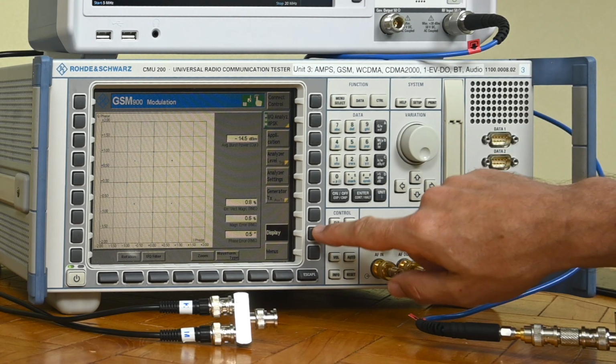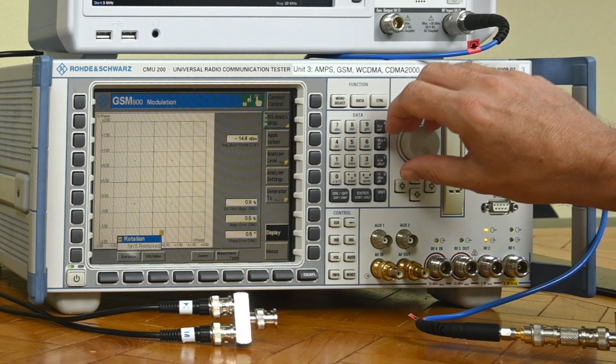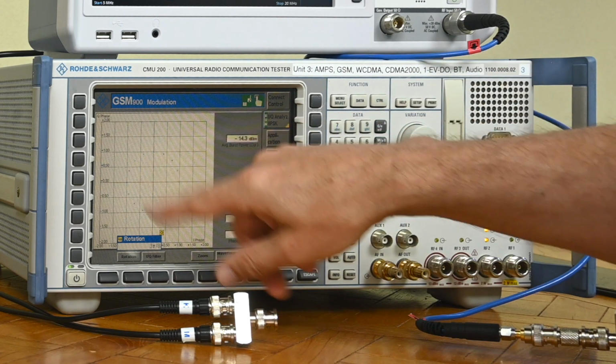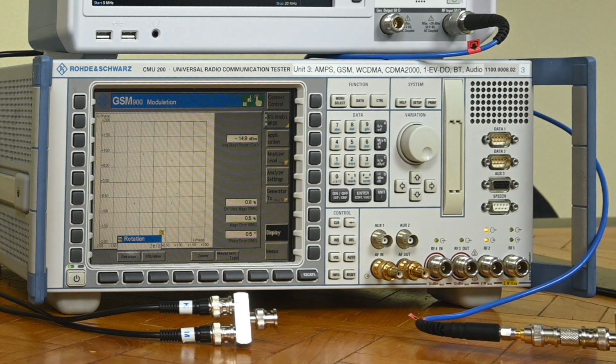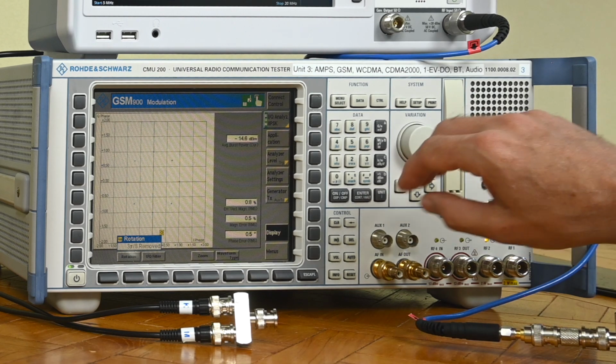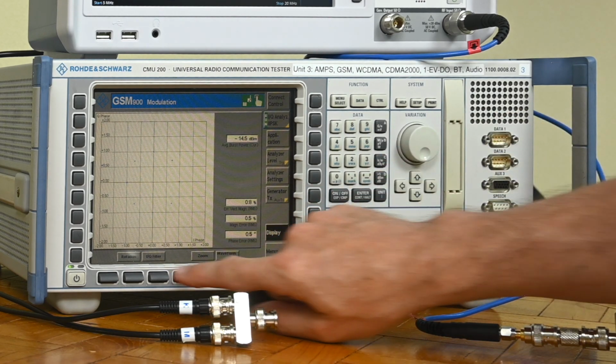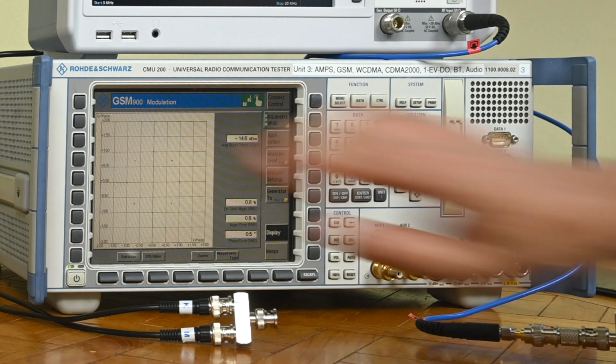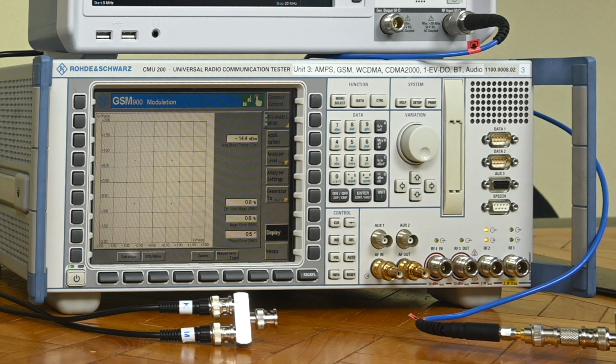There are a number of things you can do here graphically with it. Actually, you can do this, and you see more. This has to do with the way that 8 PSK is realized within the GSM standard, because I think they do some pulse shaping and these types of things matter. So we'll just keep it here, and you can do some ISI removal. But what I'm interested in right now, and I hope you can see it well enough on the video, is the constellation diagram here with its concrete values.